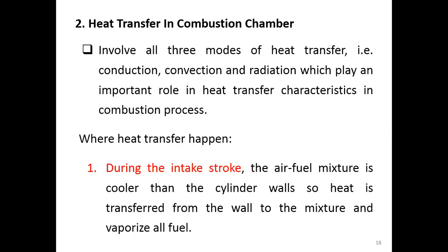So we have heat transfer from the wall to the mixture, and this heat will help vaporize all the fuel. Apart from the intake manifold that helps already, we have more help from the heat transfer, where this heat comes from the wall to vaporize all the fuel here.